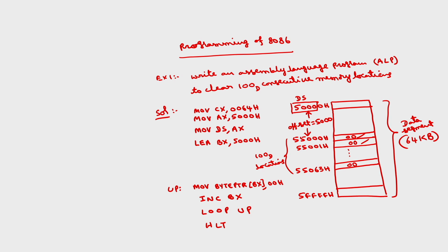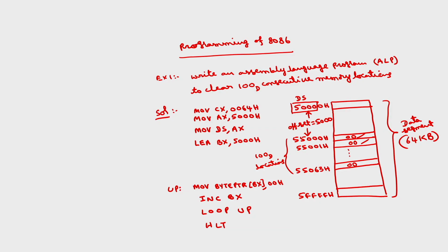You have to choose the appropriate locations. This is one way. Word PTR and byte PTR are called assembly directives. If you want to write this using an assembler, you have to specify byte or word. The remaining few more programs we will discuss in the coming classes.